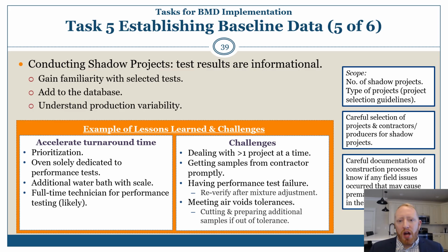Careful selection of the projects is key. You want to make sure it's the right type of project. It's not going to hinder production or impact the contractor negatively anyway. And you also need to start thinking about careful documentation, because you'll have BMD test results. You'll want to compare it to field performance in a couple of years. So if something goes wrong in construction, you want to have that well documented.